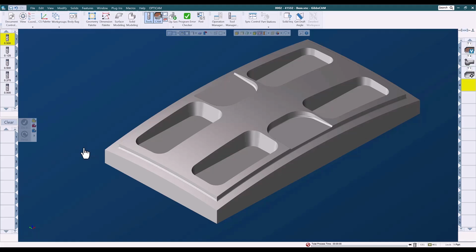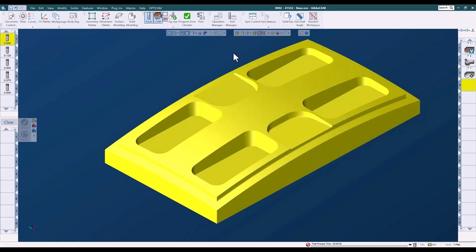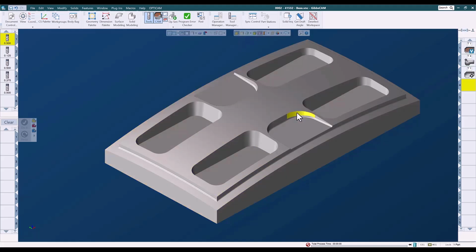What would I like to do next? I guess we could deal with these features here. I'll machine the walls and the floors here. So there are a number of ways that we could approach these walls. These are vertical. So we could do a contour, just a plain Jane geometric contour projecting the toolpath down onto this surface.